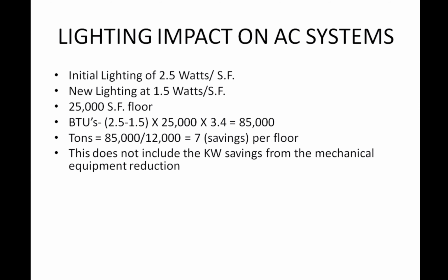Just a review kind of calculation here. Obviously when you have lighting, there's going to be an impact on the heat within the building. And we talk about the heat transfer and what that load does for it. So if you reduce the wattage that you're using by shifting to new bulbs, smaller bulbs maybe, lower lights, or even more efficient lighting, there's going to be a significant difference in the amount of air conditioning you'll need to cool those floors in the summer. So it's just something to keep in mind.